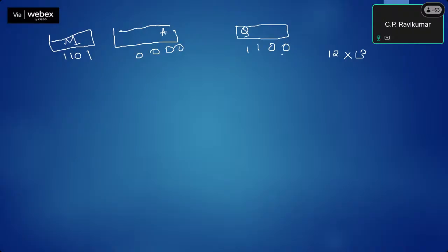Now we have to look at the bits of Q one by one. We always look at the last bit or the least significant bit. Okay. If it is a 0, we have to simply right shift A and Q. So you assume that there is a carry here. Initialize that to 0. So that 0 will come here. This last 0 will come here. 1, 1, 0. So this is a shift operation. If you see a 0, simply shift.